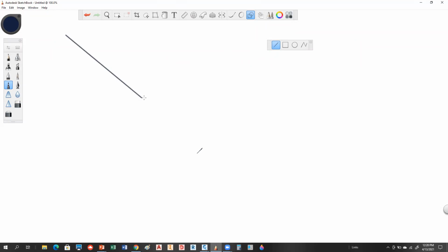Okay, so we got a grade down and a grade out. So it's a flatter grade going out than it is coming in. And we have this parabola that we're doing, kind of like that, close enough. So we basically have a distance here of 350 feet.